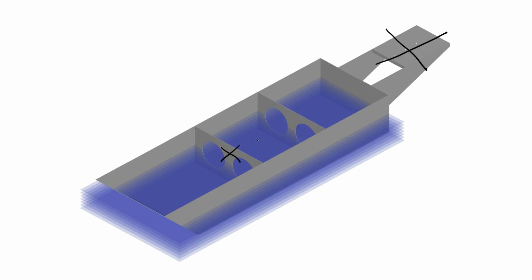Also, we're not going to worry about the bulkheads, even though they're shown in the picture, and that's of course because they're inside the hull, and the things inside the hull don't displace water. My water planes that I have shown in this diagram, there's one at the baseline, or base plane. There's another at my draft, which for my water plane areas, I'm assuming to be 6 inches. So this distance here is 6 inches. And then I have 1, 2, 3, 4, 5 more water planes, each spaced an inch apart.